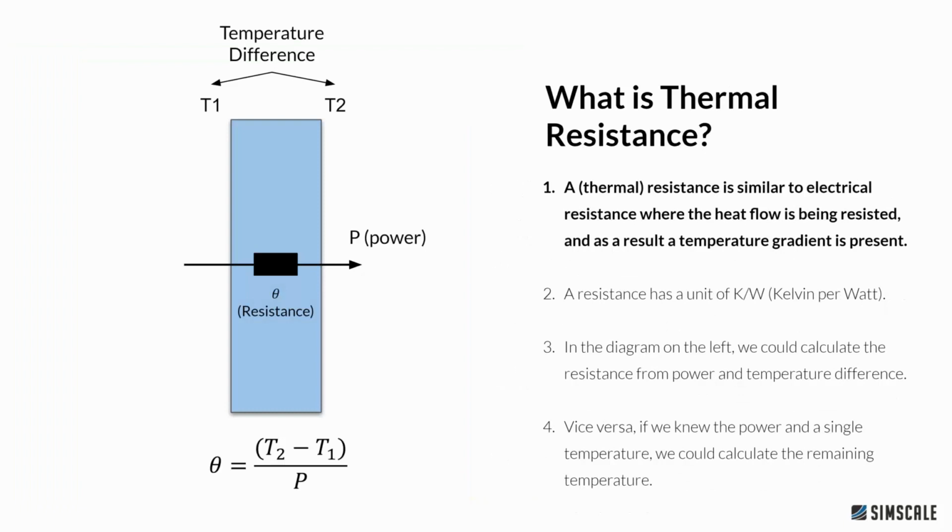So what is a thermal resistance? A thermal resistance is very crudely the ratio of the temperature difference between some point and another point divided by the power that is put through the system. If we turn that into something physical that we can understand, we could say that we are applying some power source on a face through a plank of wood.